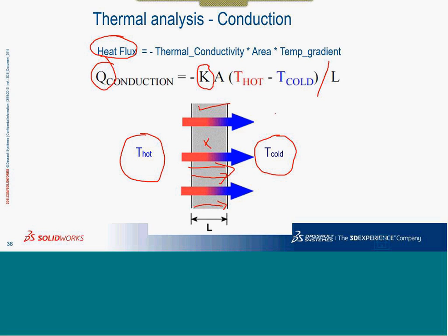What I want to highlight is that this particular thing is not calculated in SolidWorks Premium or the simulation standard capabilities. This is only in simulation professional. If you observe, this is basically the temperature distribution inside a part, or the heat flux, or the rate at which heat is flowing. Whereas in a stress analysis or simulation standard, we are actually simulating only this. So when a temperature difference is there, or a temperature changes at a certain location, what amount of strain comes inside the body is understood through this.